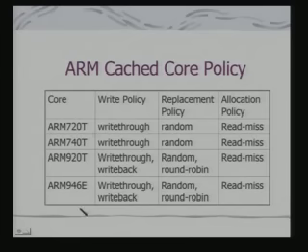Now, how are these things really implemented in a microcontroller? These policies are available, but how are they made available and how are they to be used? That leads us to the issue of cache control in ARM. If you are looking at cache management in an embedded system, you have to have these mechanisms available on the embedded controller itself to manage the cache.